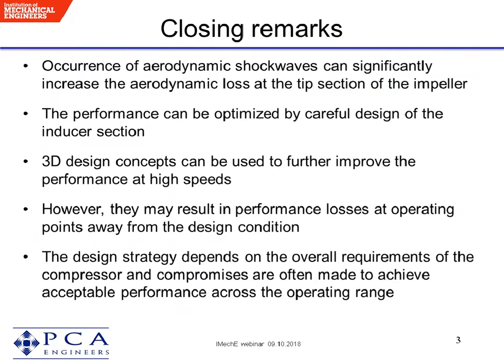The inlet guide vane is probably better because it changes the swirl coming into the impeller, and this means it can either reduce or increase the flow and the work going into the impeller. Variable diffusers are able to be used to shift the characteristic, but they have no effect on the impeller. So at low flow, you still have a high work input.